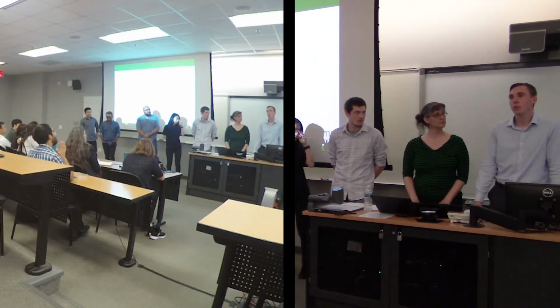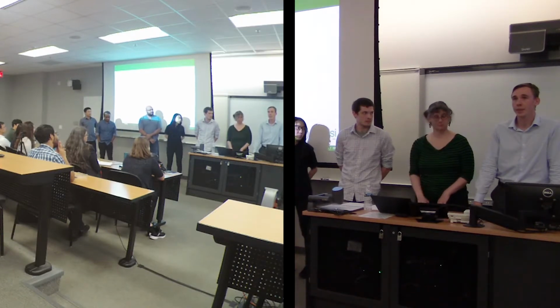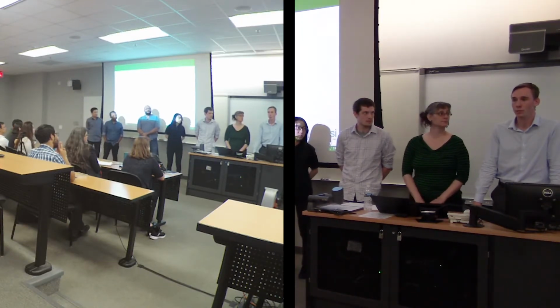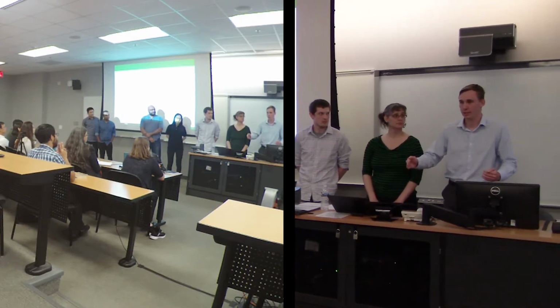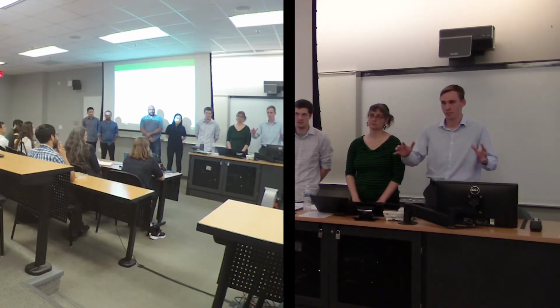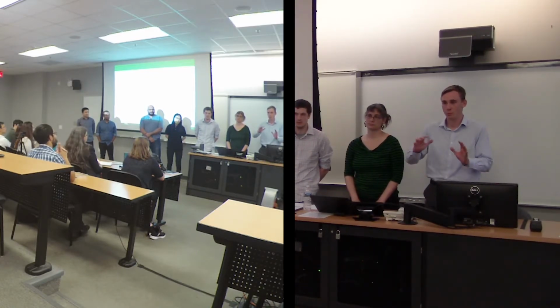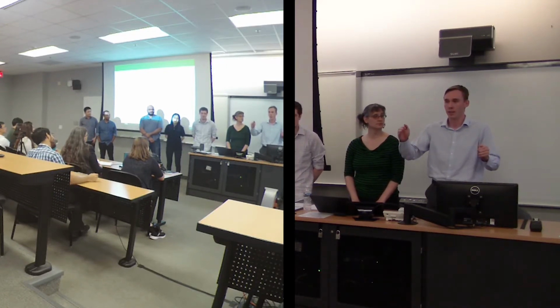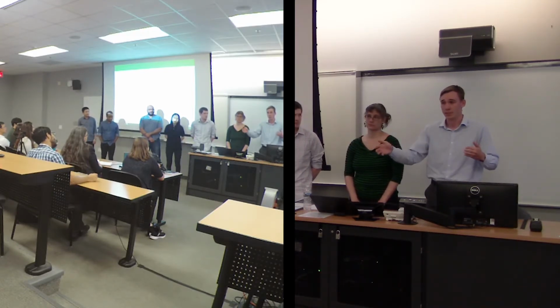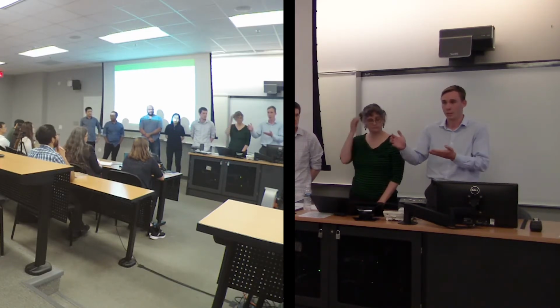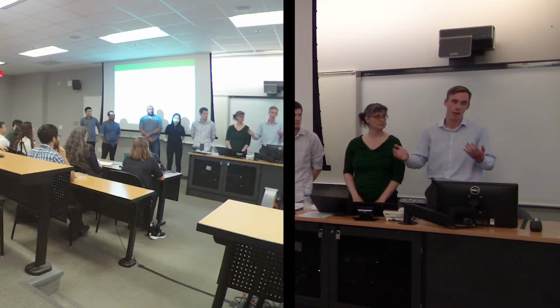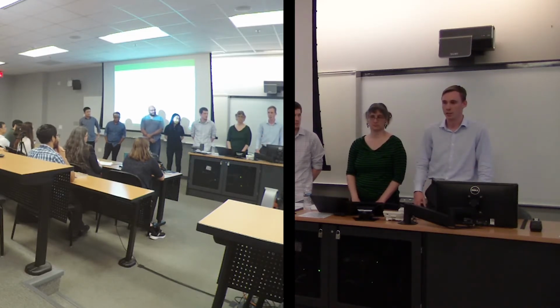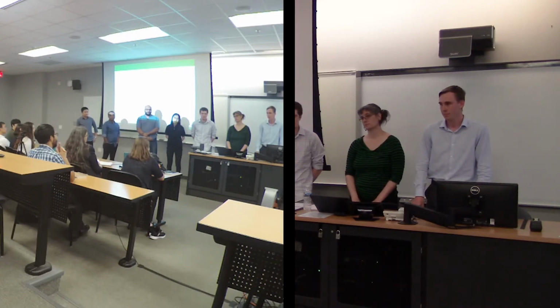That's not necessarily something we looked at so much, because in this scenario, even if you're off by 0.1 of a volt, but you're outside those constraints, then it's still going to be a failed system. They aren't soft constraints where you roughly need to be inside them. They're very hard. If you get at all above this limit, you're either going to cause a lot of damage to the system, and in the case of a lot of the generator constraints, you're going to break your power plant if you ask too much of it, or you're going to get power outages if you have any issues with buses. I see, thanks.